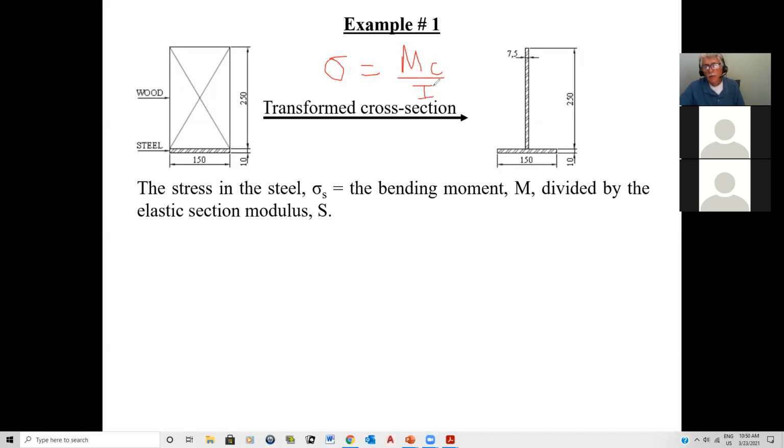That's what they probably gave you for the flexural formula. But remember that S is equal to I over C, and therefore we don't use this in engineering. We use the section modulus, okay? And therefore we calculate the section modulus, and we know that the stress is equal to M over S, and that's what we use, okay? It comes out to the same thing, but it's much easier because the books will give you the value of S in your steel and so on, okay? So I don't know if they covered that also, but that's what we're going to be doing here.